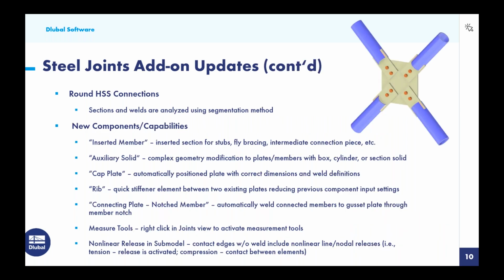We also can now consider round HSS connections. Previously, this was a small limitation that we had. So these sections and welds are analyzed using the segmentation method, and we'll take advantage of this connection today with the one in the upper right-hand corner with these round HSS members.